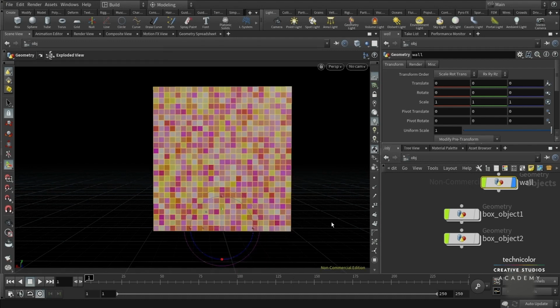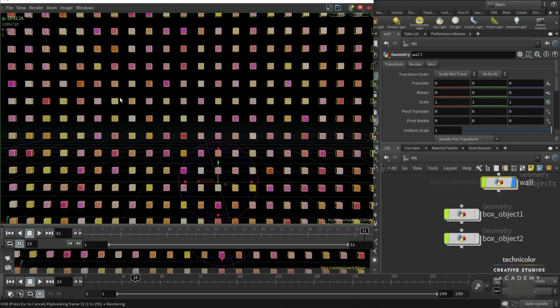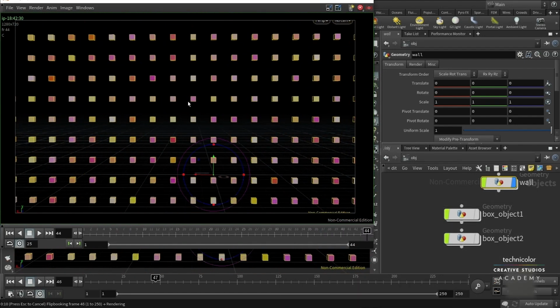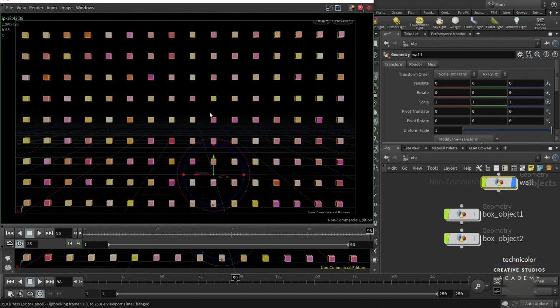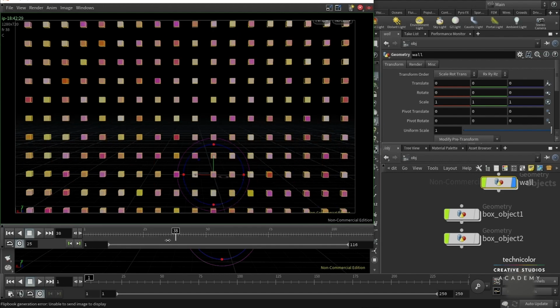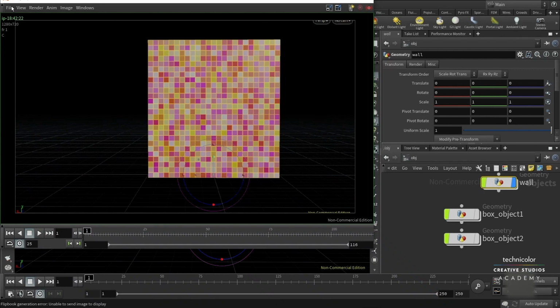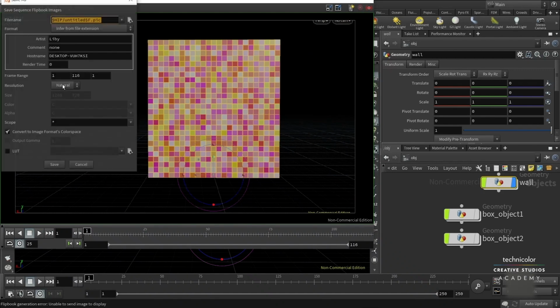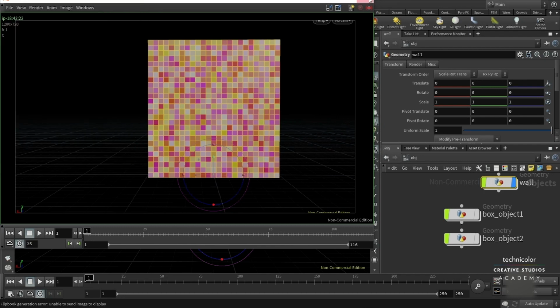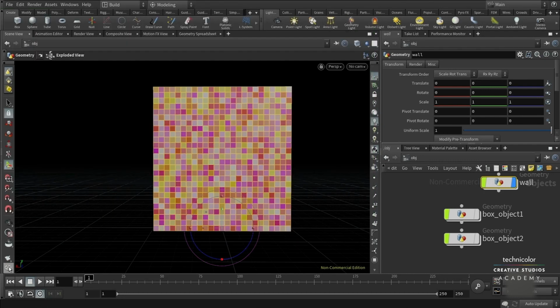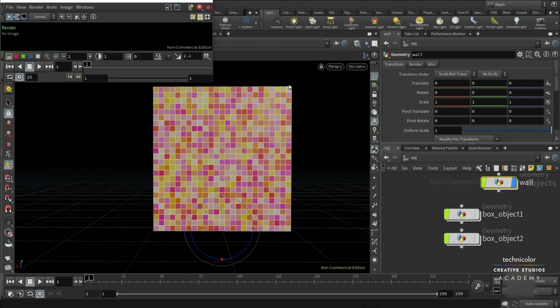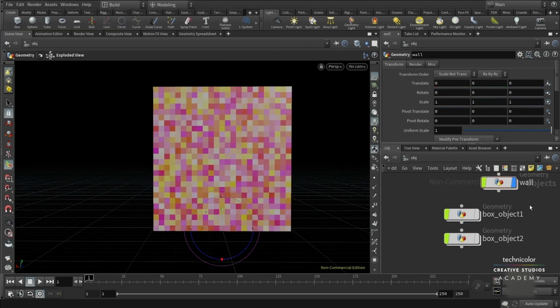This will open a separate window, and as you can see, everything that we have in the viewport is displayed over here. Okay, nothing is happening after frame 50, so I'll just press escape to cancel saving, and I can play it here, and I can also save this flipbook, so I can go to file, save sequence as, and then choose my location. You can also run renders, so just click on this film reel to open Mantra. So again, a separate window where you will see your render. Okay, and that's it in the introduction to Houdini and its interface.